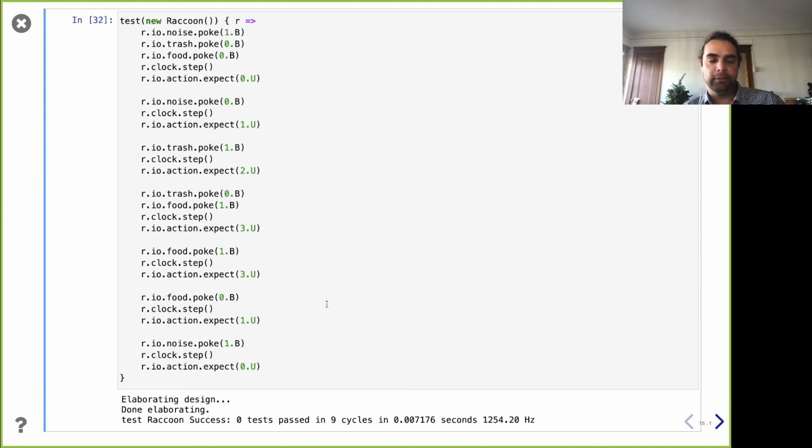Next week we can cover testing, and some more sophisticated ways to deal with these state machines and test them. It's a whole other topic, but these simple constructs of poke, step, and expect get a lot of the way there for creating these tests. I personally have a convention of liking to put new lines that distinguish behaviors across cycles, like mini test cases. Typically, you might have step on the last line of a block, but I chose to see the results of the prior interaction. I want to see how it changes the output. That's why I put the expect for the state right away.